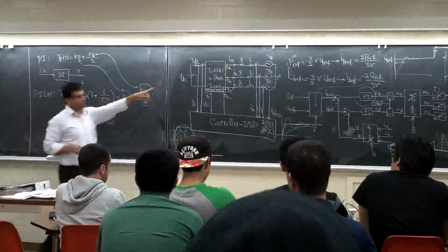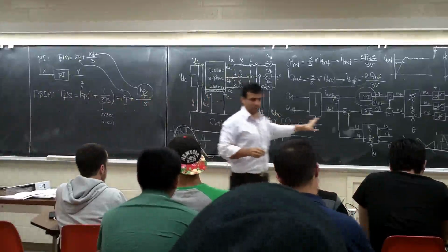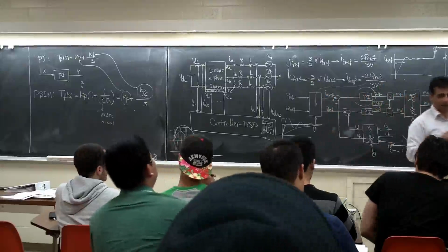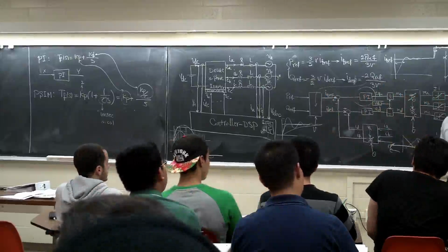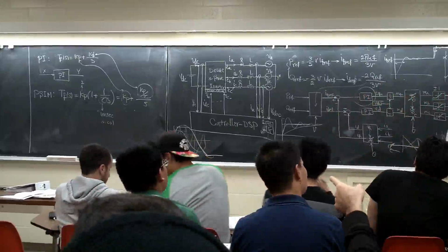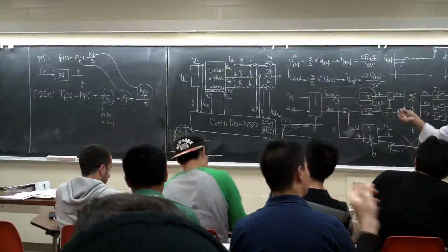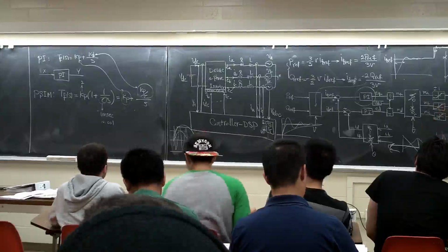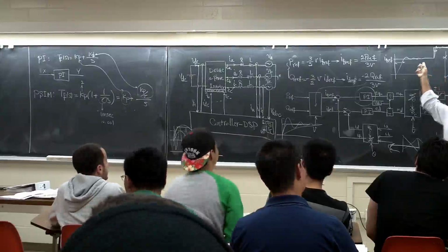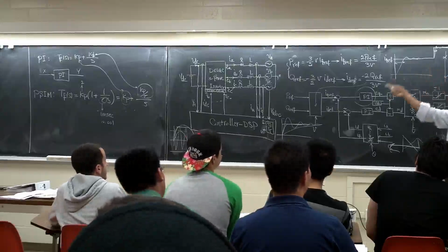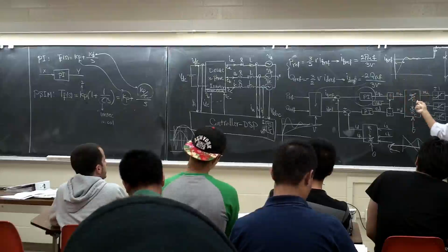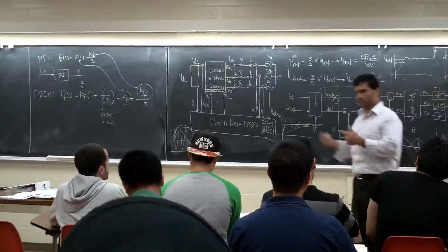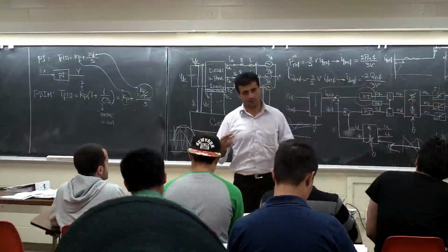It depends on the inductor value, the switching frequency, those kinds of things. But you can start with this one if you're going to start blindly, without any control design. We have to change the value to find it. For example, keep the tau at 0.1 millisecond and start to see. If you go a little bit over with the K, it gets worse, so bring it way down. This is trial and error. This is what we are doing: trial and error. We go a little bit up, a little bit down to get it where it is.